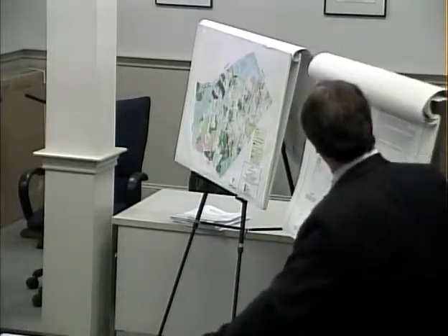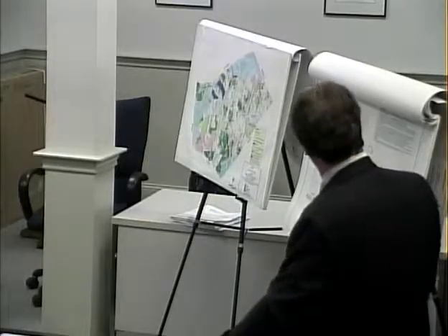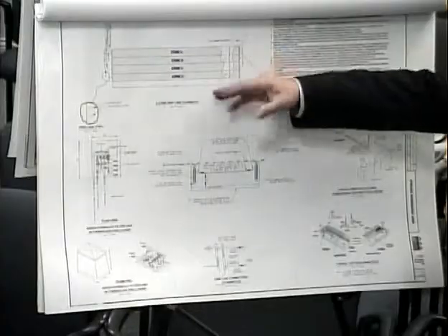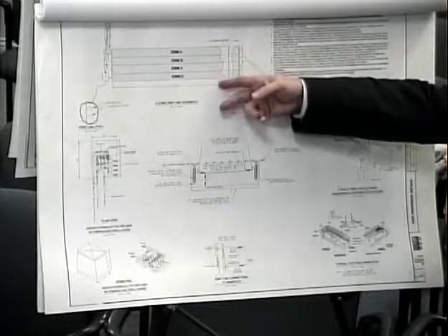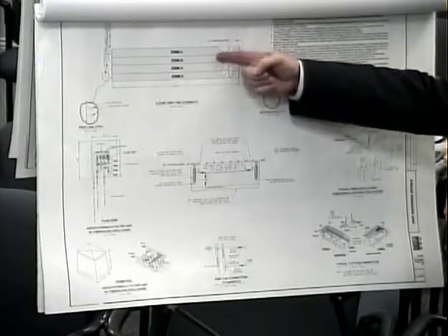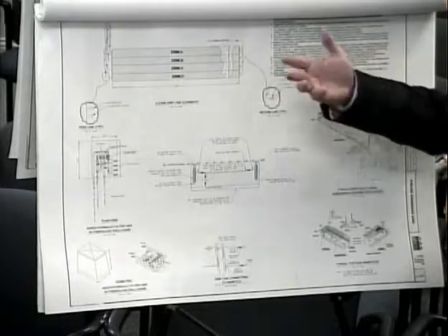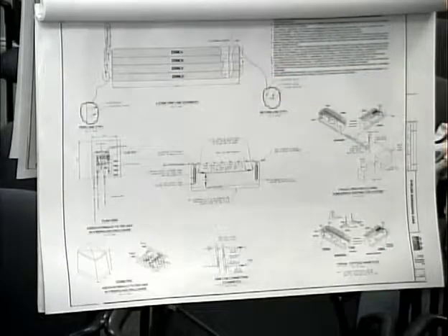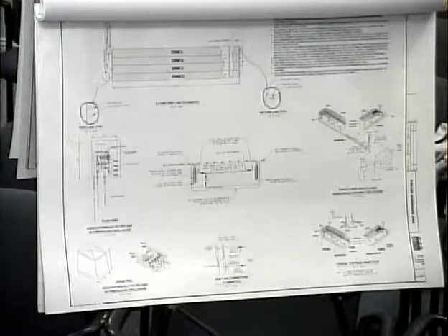Just to give you a little idea how the drip system works, I gave you a couple of details on another system. We usually do them in zones, so that you dose one zone, the next time you dose another one, next time another one. It allows you to distribute the flow throughout the area and helps to keep your mound down instead of applying it all at once in one location.